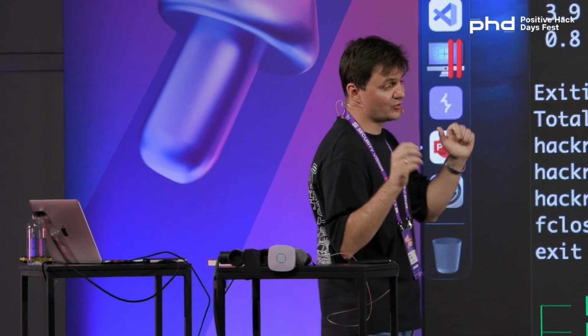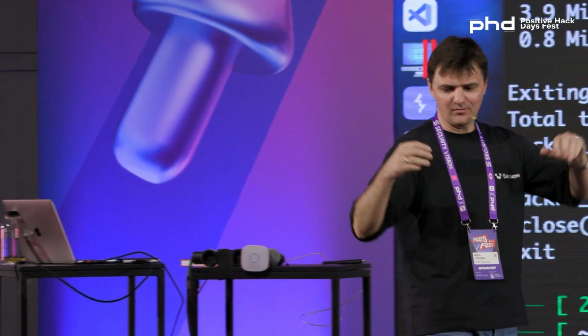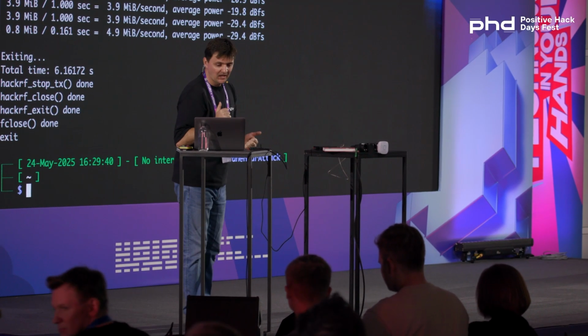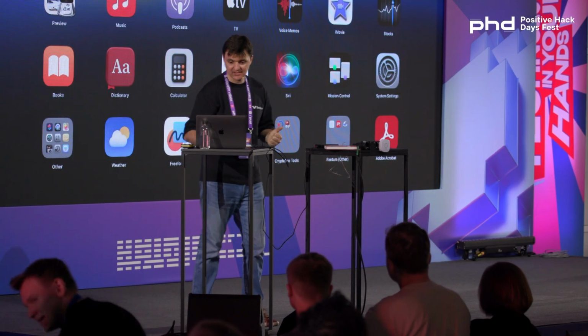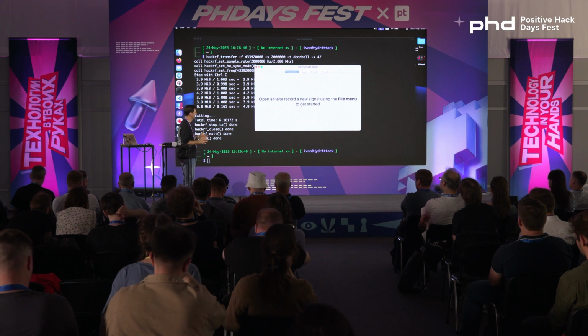Are you pressing it? No. No. No magic. Everything works. In this case, we carried out a simple attack, replay attack. We received the signal, recorded it, and then we retransmitted it without thinking what is inside. Replay attack. Now the same attack, but we shall look inside the signal.